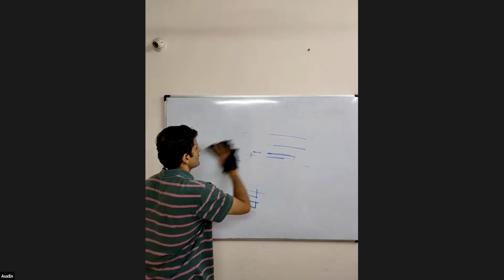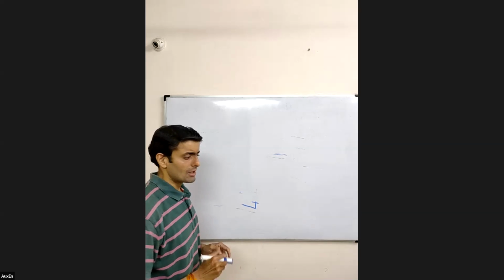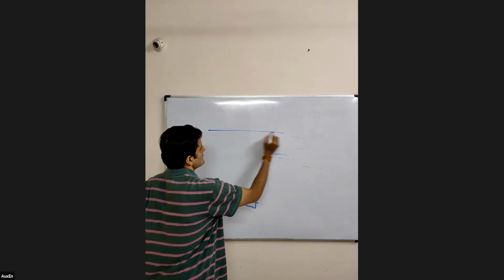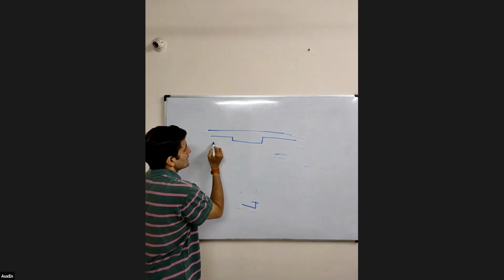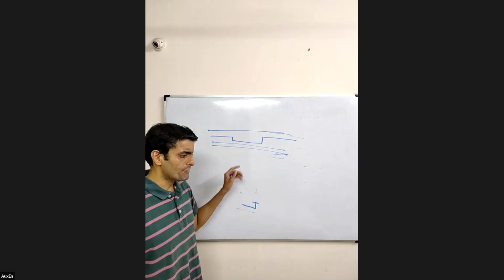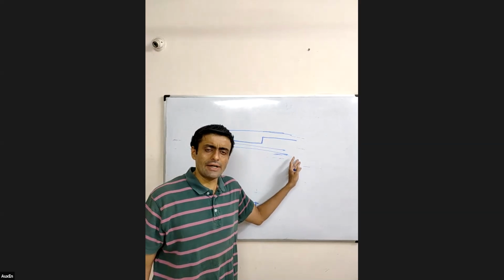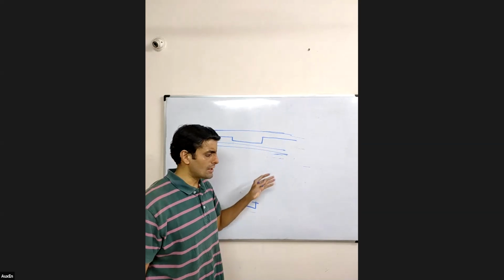So how does my flat slab system help me with this? Since I am providing a very thin drop like this, I am easily able to take my service lines right through this without making any level differences or cutting any sleeves.